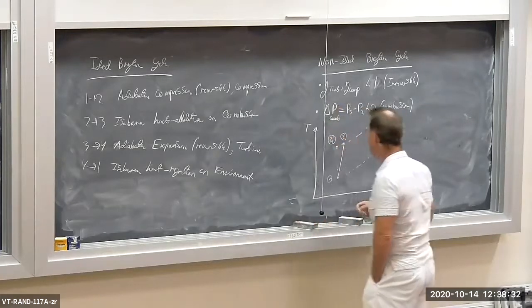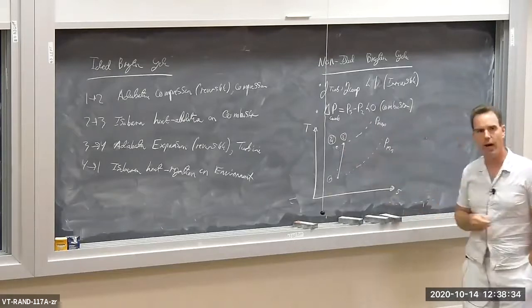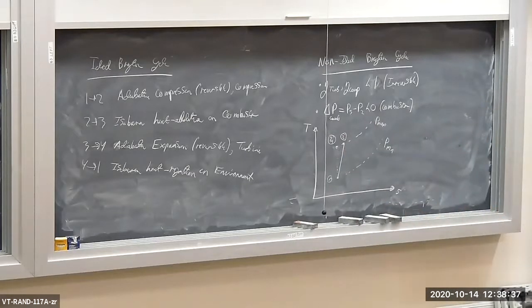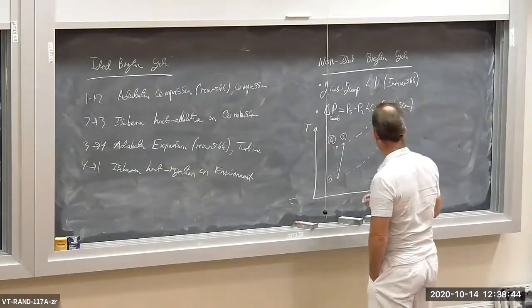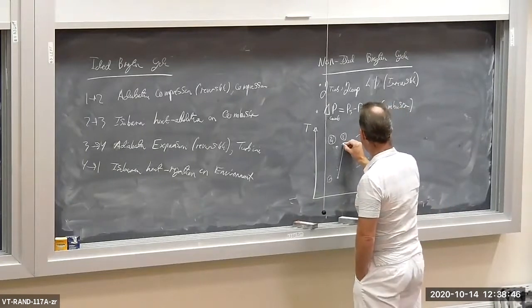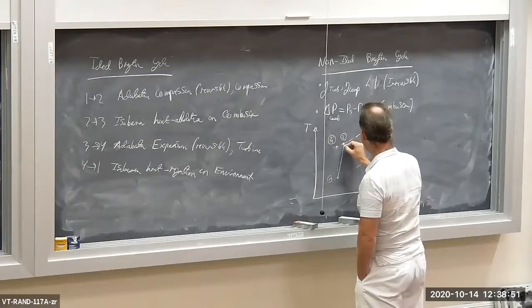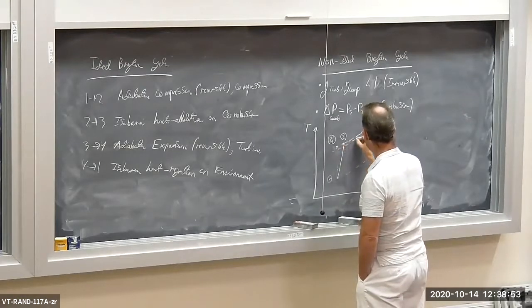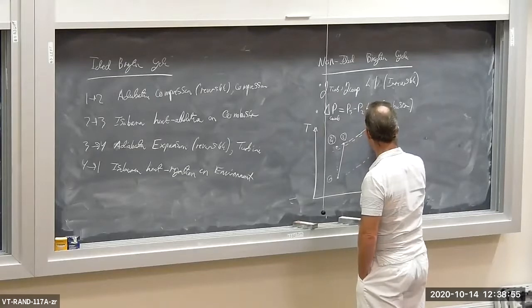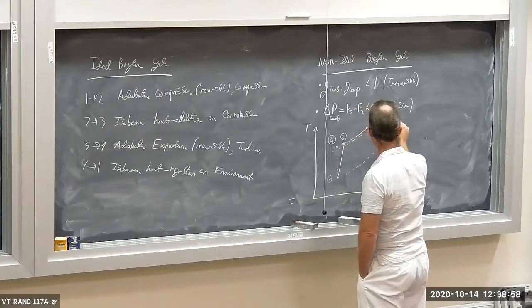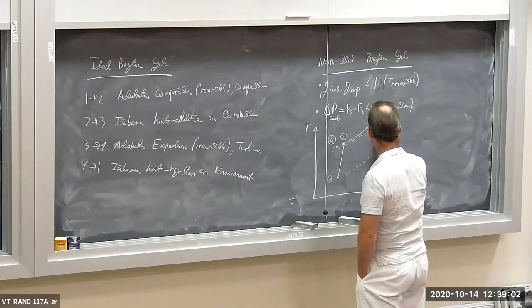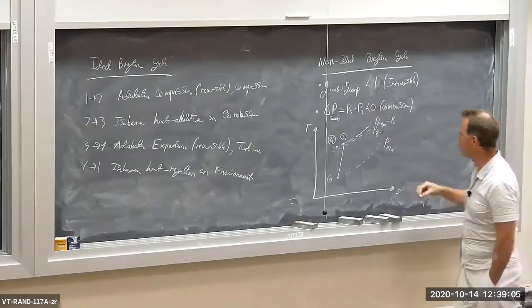So here's state 2 right here. There's 2 sub S, that's the isentropic. That helps us define our isentropic efficiency. We've done this stuff before in the chapter on entropy when we talked about turbines and compressors. Then we have maybe a pressure drop. So here's P max is equal to P2, and here I have P3. There's our P3 isobar. So we have a pressure drop.